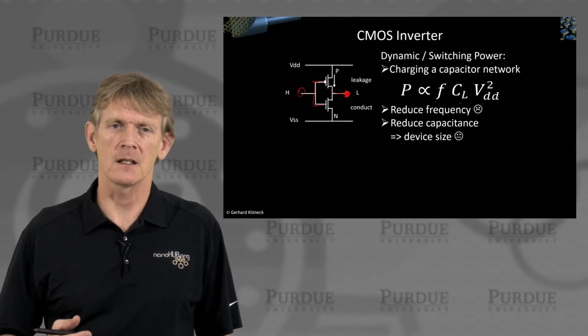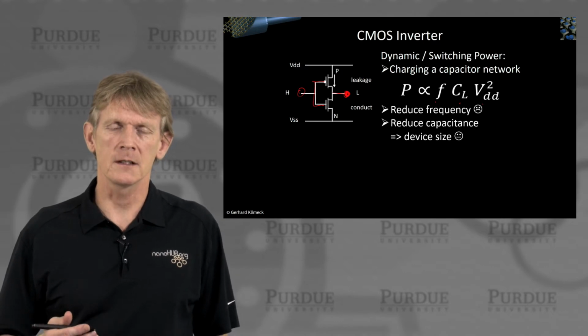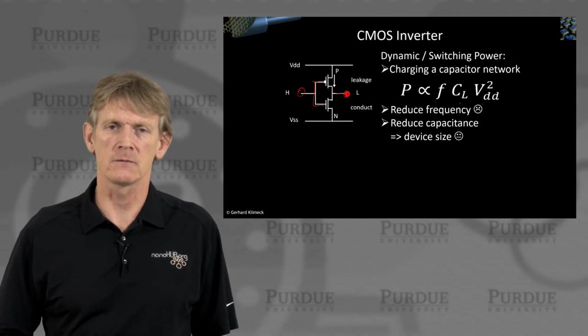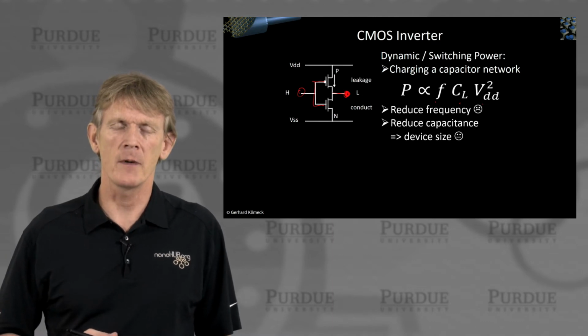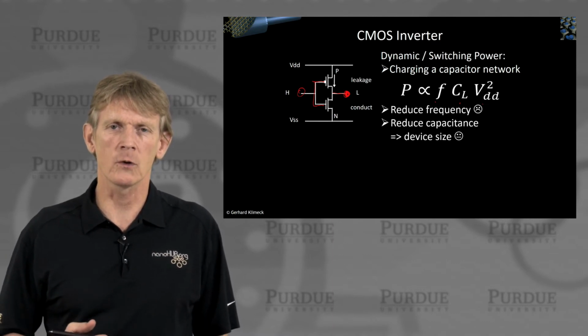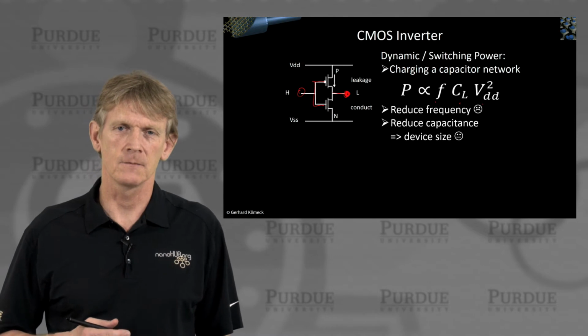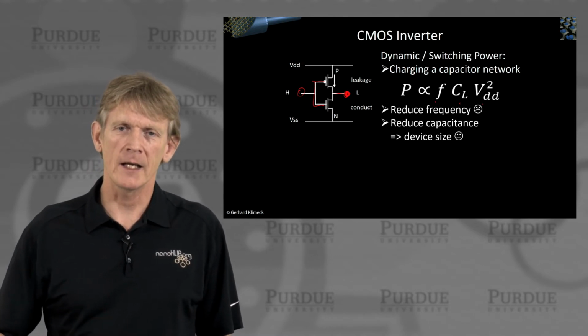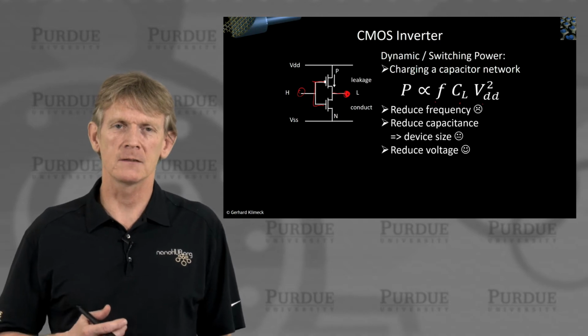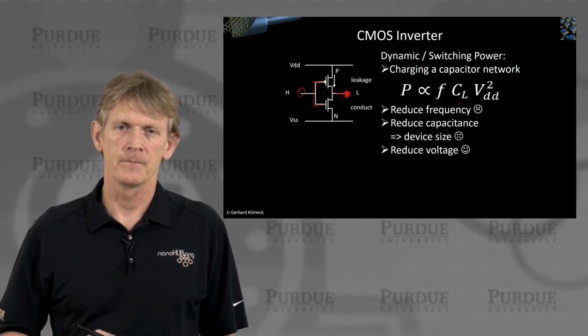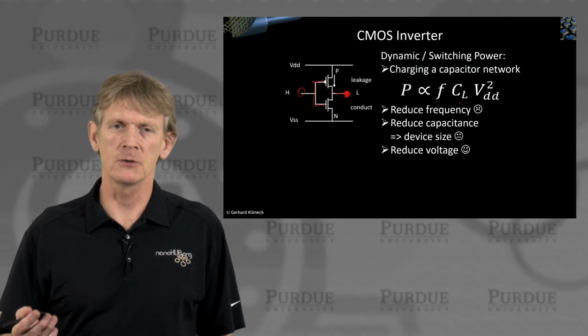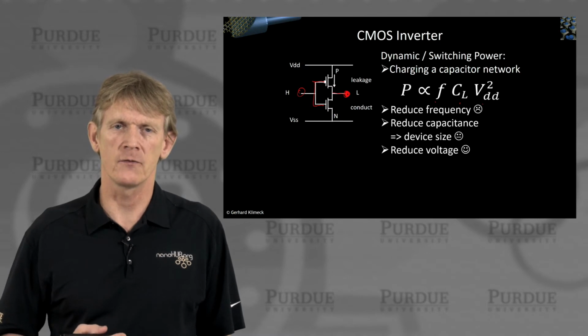And in the next subsections, I'll talk a little bit about a lot of that work in more detail, as short channel effects and threshold voltage control, etc., have demanded technology advancements. But it's a lot of work to do that, and it's still going on today to optimize technology, get smaller transistors. But what has happened for some 30 years was a relatively easy step: reduce the voltage. Just to put this in perspective, if you reduce the voltage by a factor of 2, you reduce your power consumption by a factor of 4. So that's quite significant, to reduce the voltage in your system like that.